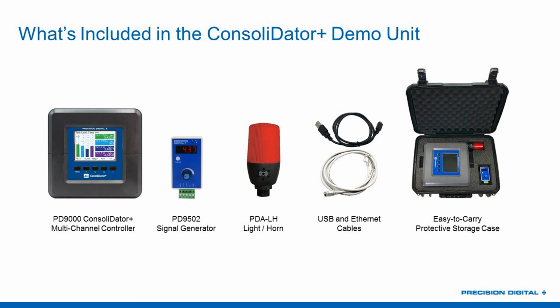have 10 Modbus inputs, and you could tell it to read 4001 and 4002 as a float as one Modbus input, and the second Modbus input would be 4003, 4005 as the second Modbus input, etc. You wouldn't rack them up in like a coil read or anything like that and say, hey, go get those 10 values and display those 10 values here. You just program them up as 10 individual Modbus inputs.